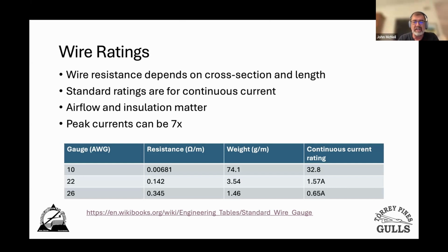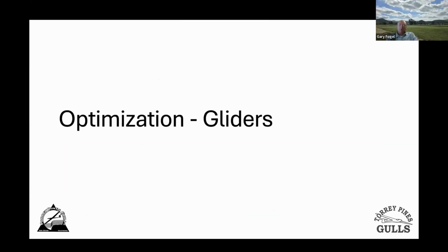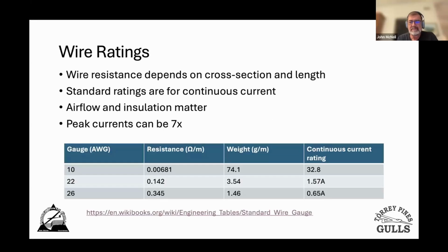And there's a good table that I use in the link there. There's a question. John, is now a good time to ask another question? Absolutely. When a pack puffs, what's going on there? The short version is that's hydrogen collecting in the cell. Now, why is hydrogen collecting in the cell? It's because of electrode damage, and the electrolyte is starting to come apart into its components, which includes hydrogen.